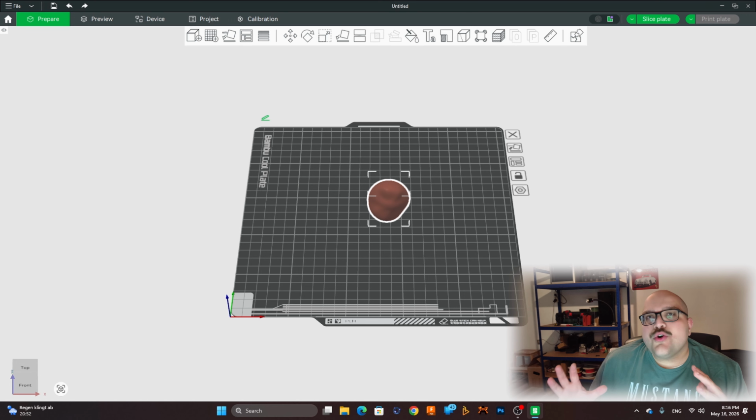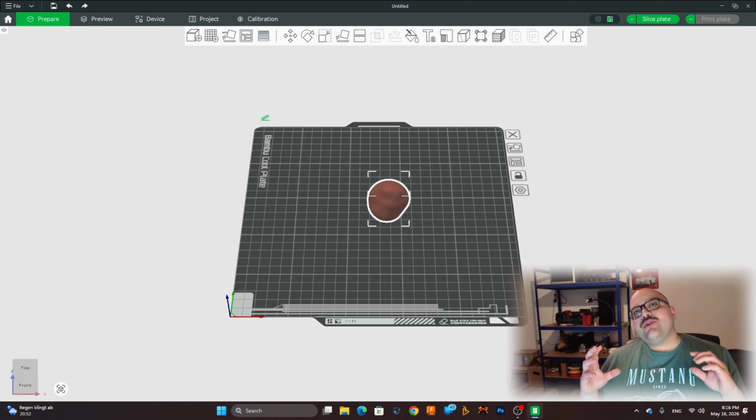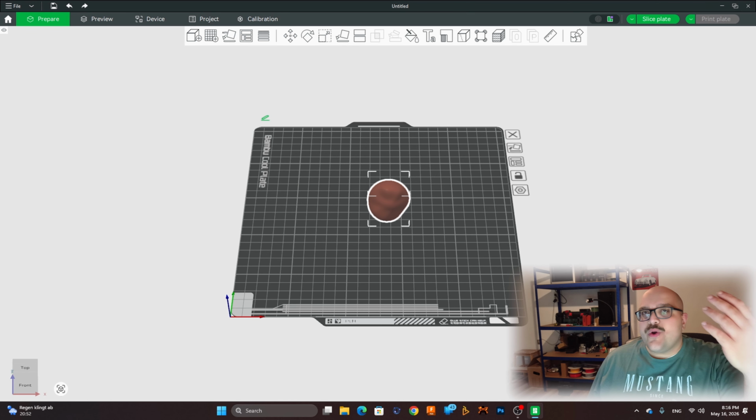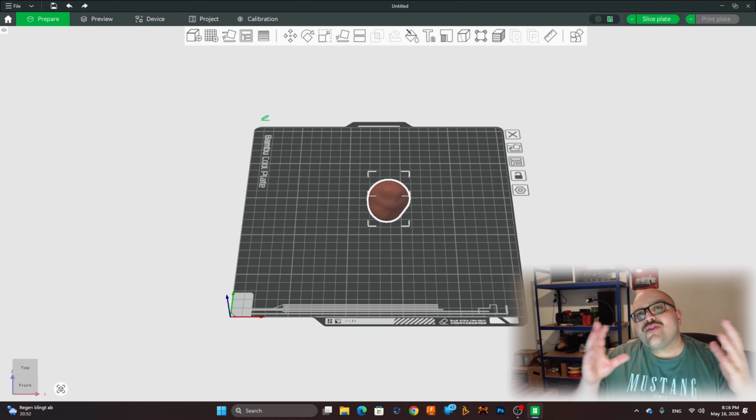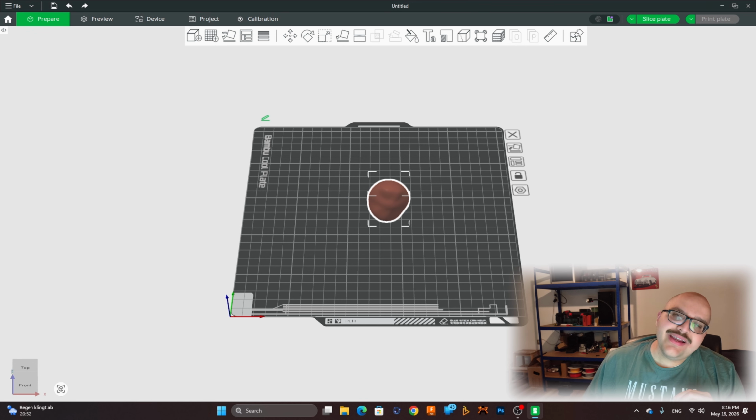So, to get your geometry to be printable by your printer, you have to slice it down, therefore the name slicers. What it does is take the geometry and create distinct layers of either set or variable heights. Those layers get further transformed into Cartesian coordinates, and based on the printing parameters, they can translate it into tiny slices of material of the item you're creating, and those layers are superimposed upon each other, which ends up creating your 3D printable item.